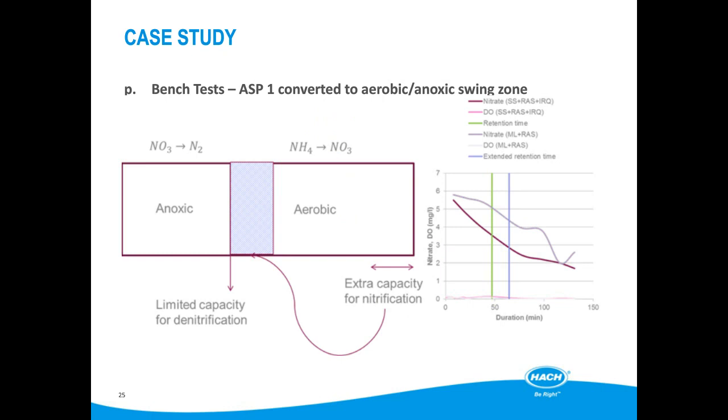So it was agreed that a good approach would be to balance the priority between aerobic and anoxic volume. By converting aeration zone 1 to anoxic, the minimum retention time was expanded sufficiently to allow significant denitrification to take place, allowing the target set point to be met. Using both the dynamic internal recirculation flow and dynamic anoxic volume, even greater levels of ASP performance were achieved.